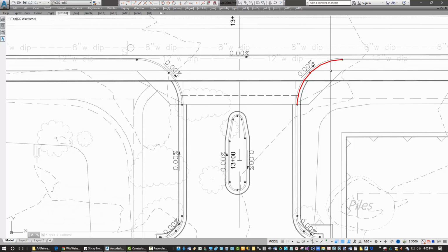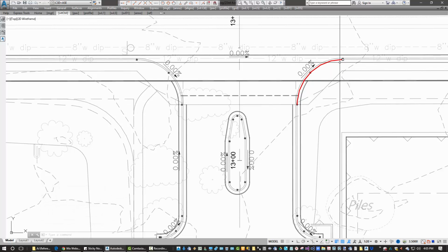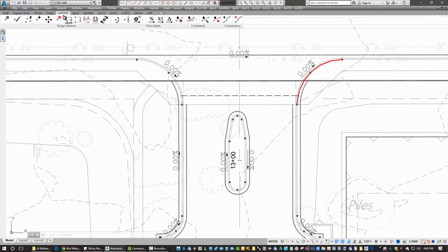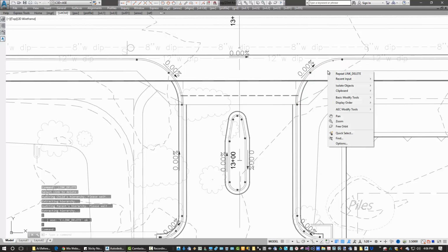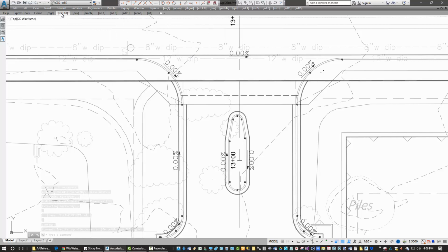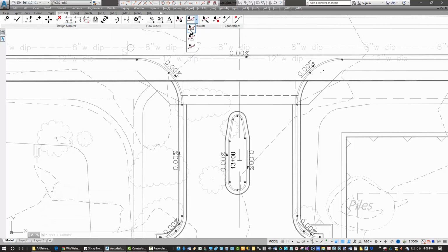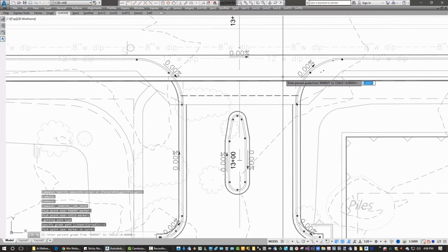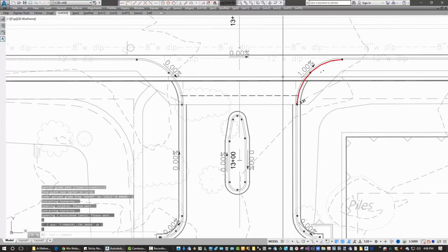Now in this scenario, we've created a constraint starting here and ending here. However, since this will likely be an existing elevation that needs to be matched, we'll take this constraint and reverse it. So there's no reverse function on the constraint. So to change the direction in terms of the hierarchy, you'd actually have to delete the constraint first. So now we'll recreate it in the correct direction. We'll start at the existing, go to the finished ground through that curve, and we'll say 1% here.